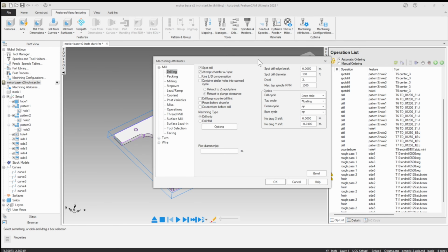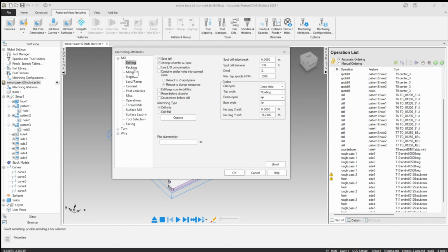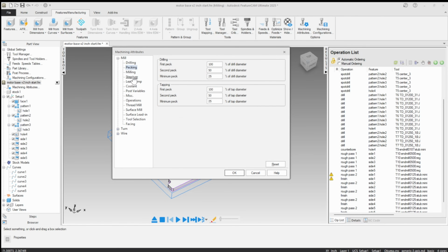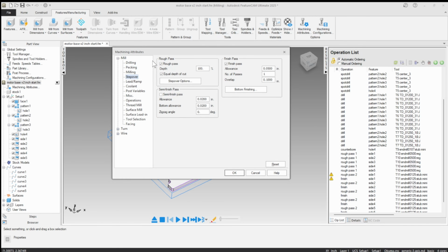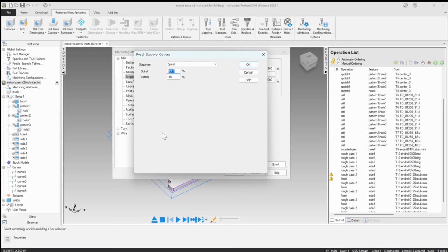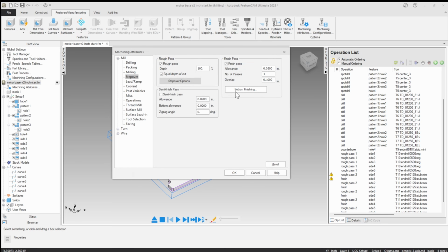One of the things I want to point out is in here we have a step over. This is the depth of cut. We're doing full tool diameter as the depth of cut. Now in 17-4 or stainless 303, that might be super aggressive. So I would modify these settings, or I should have just loaded the configuration that corresponds to what I want. So that's where those are, and this is your step over. These are just examples of settings you might change.